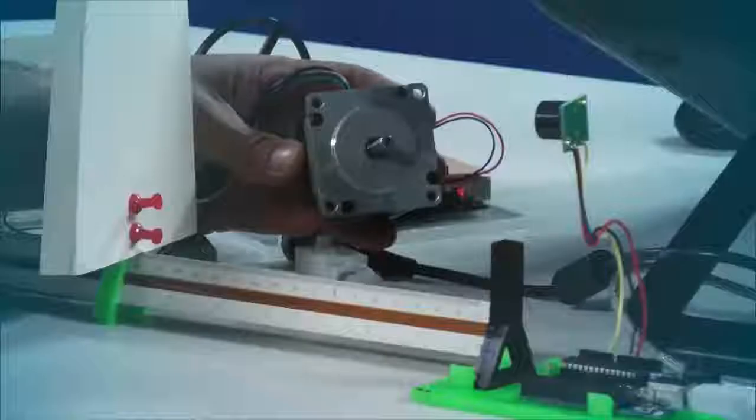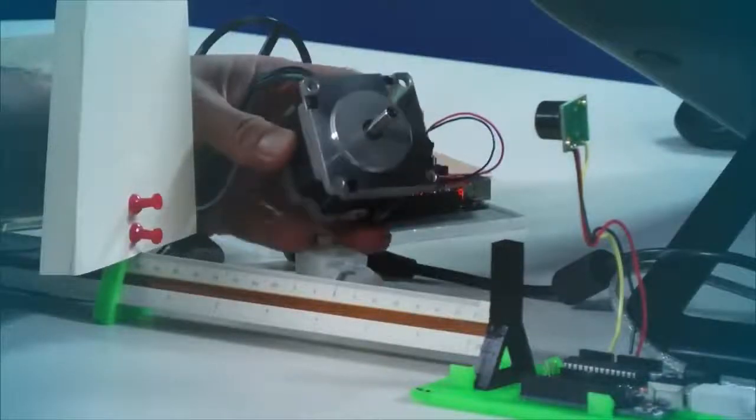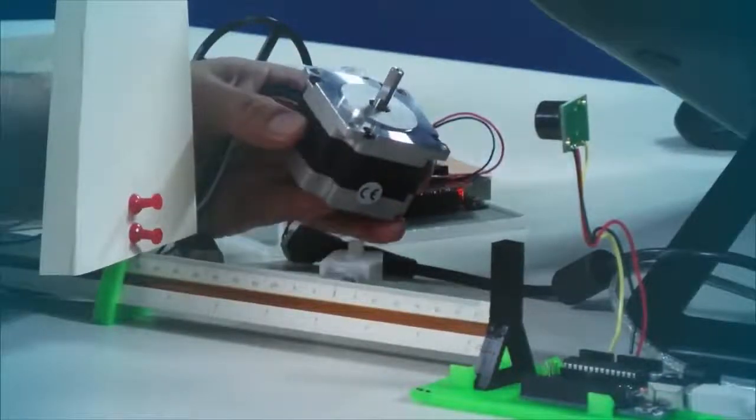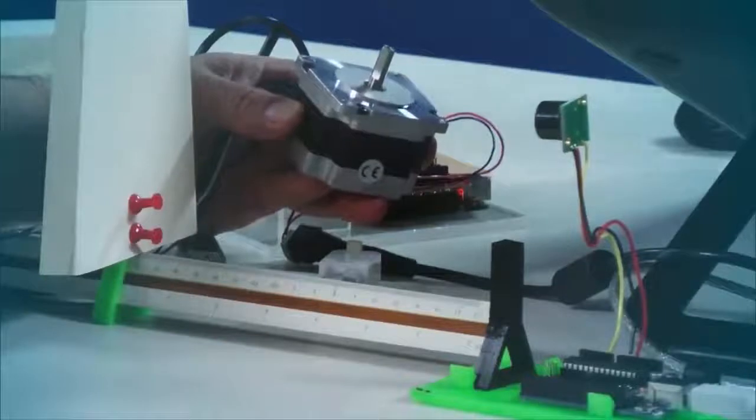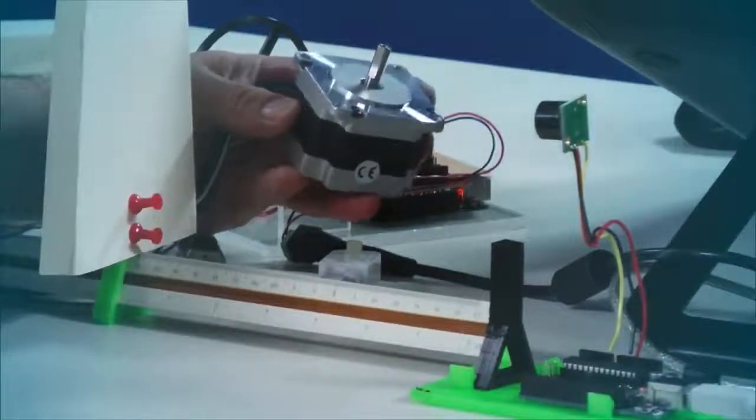which allows them to very precisely detect the orientation of the motor relative to its fixed location on your robot. A lot of them are 200 step increments, so 360 degrees divided by 200 steps, and they will track the rotations past multiple rotations. So it'll keep track of a lot, if it rotates 3 rotations plus 40/200ths of a rotation, right? And it can be very repeatable.